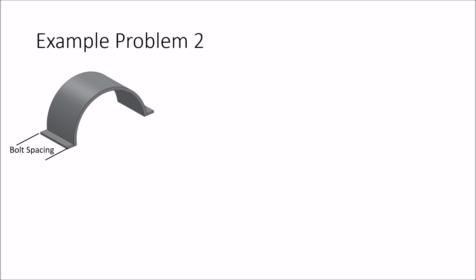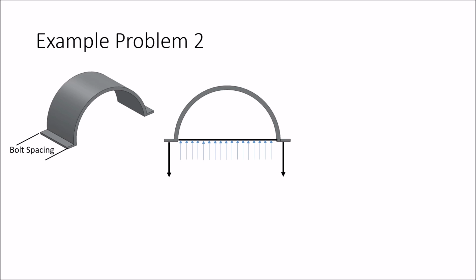Next, we will look at the orientation. You'll notice how, if I put force on either side of the pipe, that it is because there are bolts on either side of the vessel holding it together. That force will be derived from the diameter of the bolt and the maximum stress that each bolt can handle. Then we will take into account the pressure that is pushing against the pressure vessel. I purposely put the pressure on the bottom face because that will help facilitate calculations.